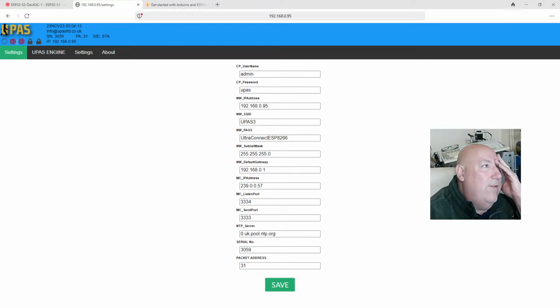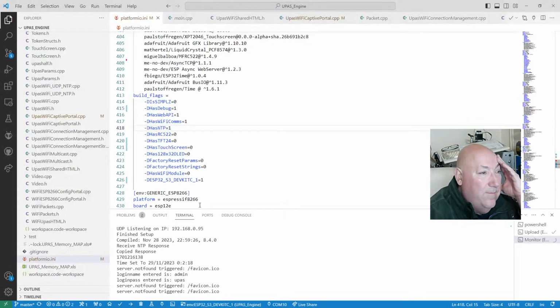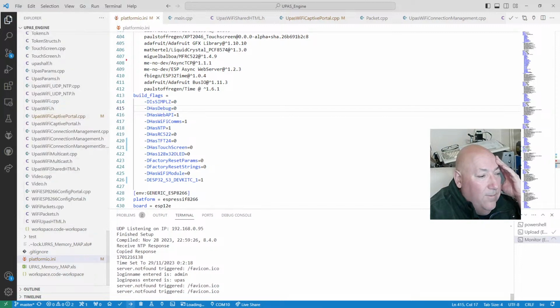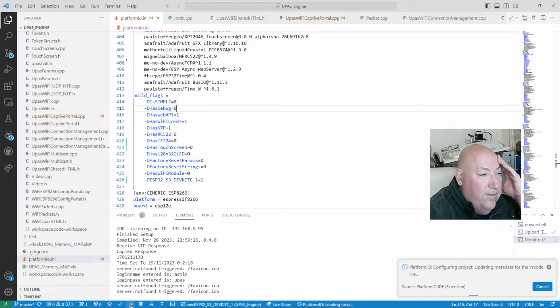See how fast these are flipping. Now, I'll tell you what I'll do is we'll recompile without the serial port on. So we'll switch the serial port off. Serial debug, right, so switch that off and we'll see if it starts going crazy faster, because the serial debug does slow it all down a bit.